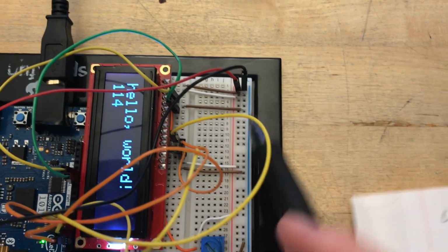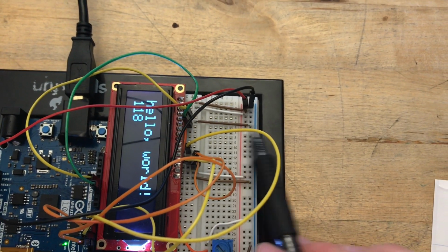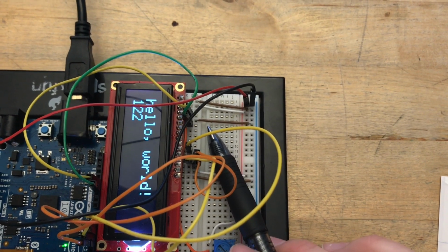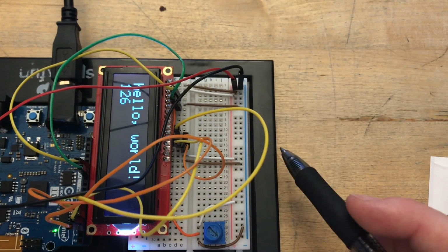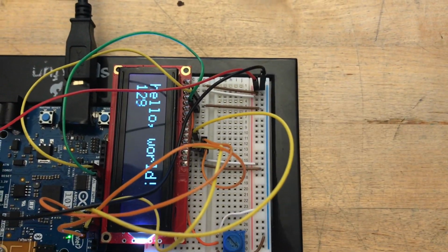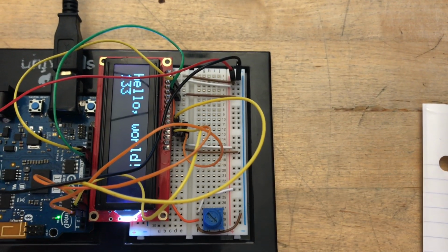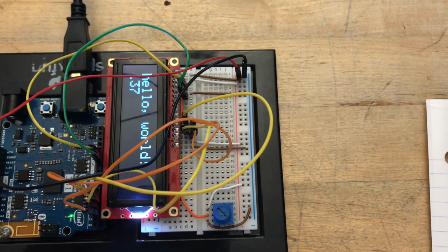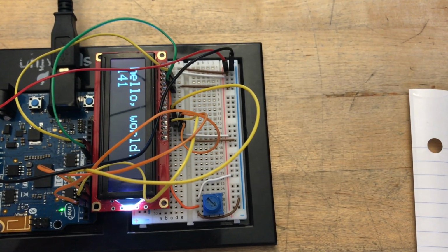The next is this brown wire here, and it's grounding the board again by connecting to this negative column. Pin number 5, which it is connected to, is the read/write input, active low. That's the function for that. Then we're going to get to this green wire here. That's connected to pin number 6 on the board, and that's the start signal for reading or writing data.